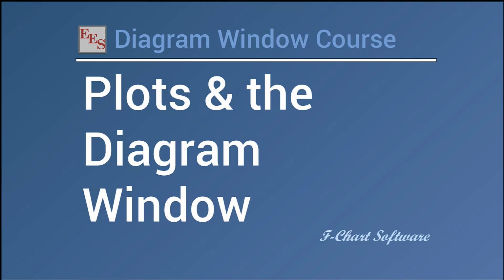Your GUI is meant to display the results of some underlying EES simulation to a user, and often this is done best using a plot. So a plot access button can be placed on the diagram window, and that allows easy access to a particular plot window that updates in response to the results of a calculation. Or, if you have the professional version, you can just put the plot itself on the diagram window.